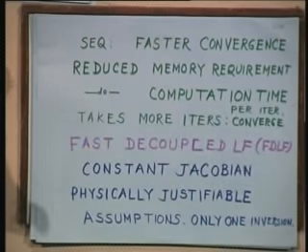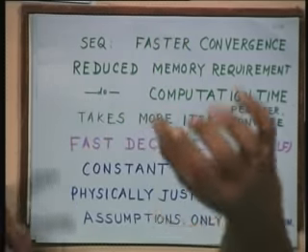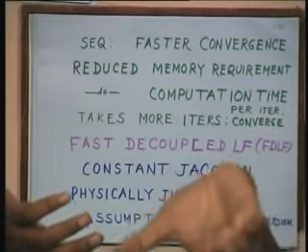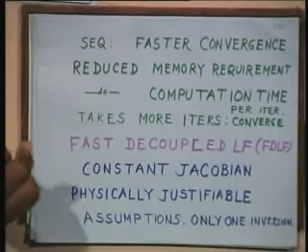And there are certain conditions which make it possible. Those conditions, of course, we will look in the next class, and I am not going to do it today, but let me tell you, conditions are same. Resistances can be ignored as compared to reactances, or deltas are small. These are the various justifiable assumptions, and G can be ignored as compared to X. That is same thing as R and X. So, we will see what are those conditions.